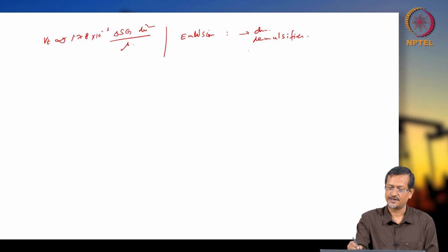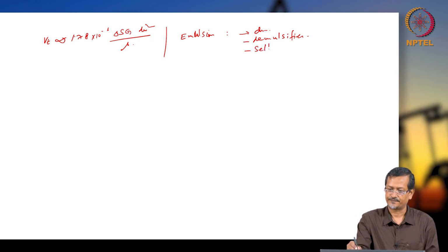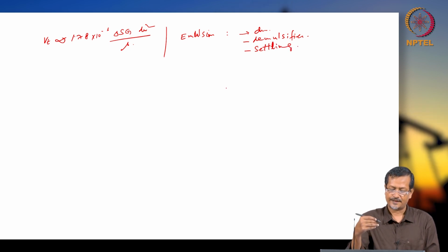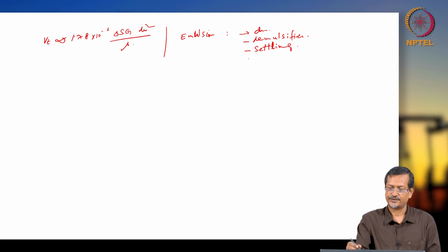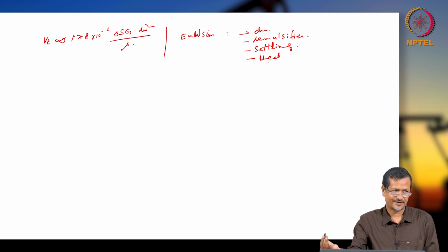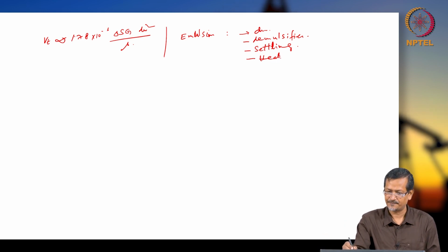Based on that you can give settling time. And when you are treating emulsion, you can use heater treater along with your electrostatic treater.